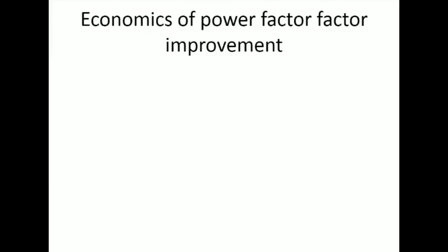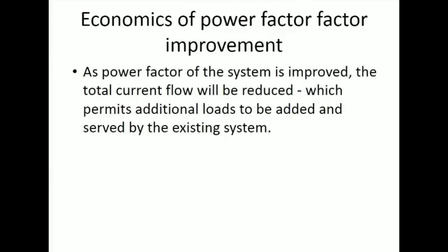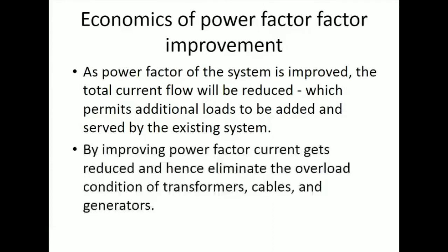Economics of power factor improvement. As the power factor of the system is improved, the total current flow will be reduced, which permits additional loads to be added and served by the existing system. The load current will be reduced, so total load on the system will get reduced. So we can have additional loads. By improving power factor, current gets reduced and hence eliminates the overload condition of transformers, cables and generators.